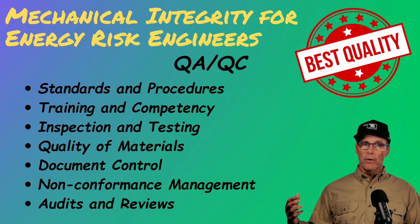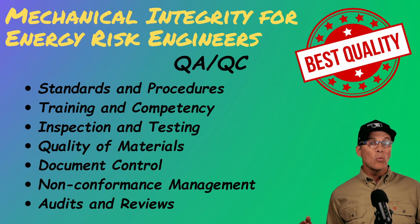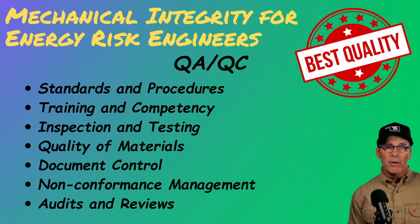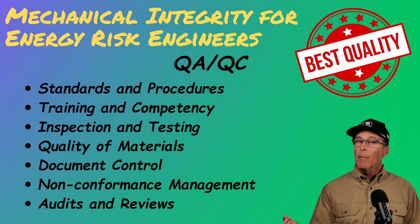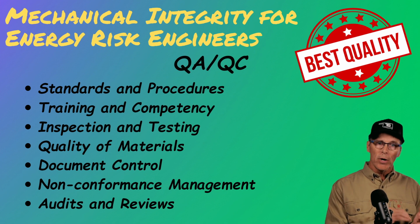We're going to make sure that people that are inspecting the work actually know what they're looking at. We don't want someone inspecting a weld who's never seen a weld before. So we're going to train them on how to inspect and test. We're going to manage quality of materials. We're going to make sure that we use a positive material identification gun, PMI gun, when we have something that's a special alloy. We want to make sure before we put it in the warehouse that we know what it is before it goes in.